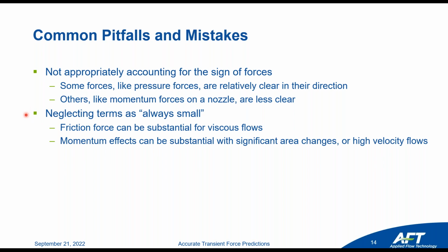The common thing, neglecting terms as always small. This is really perhaps the main way people would end up with the endpoint pressure method and say that that is totally fine, is that the pressure forces are often extremely dominant, and sometimes these other terms are very small, and that's not a big problem to ignore them. But other times they are very substantial, which we'll see in an example here shortly.